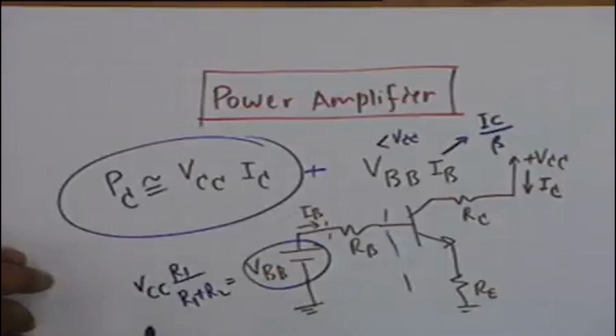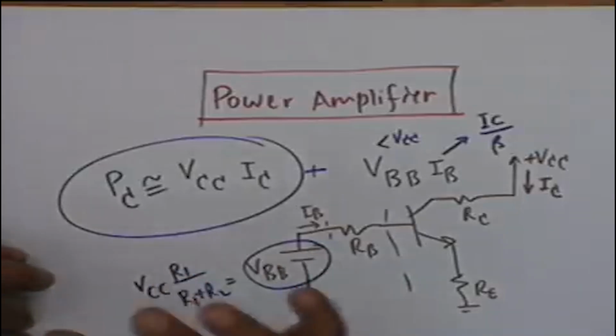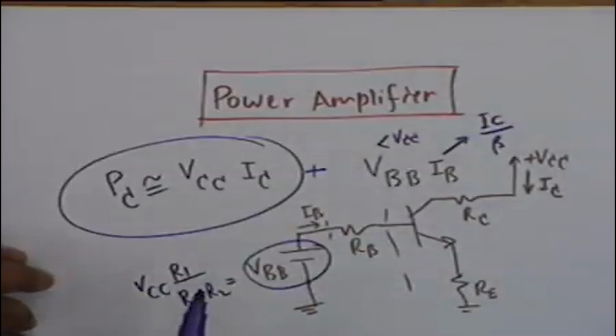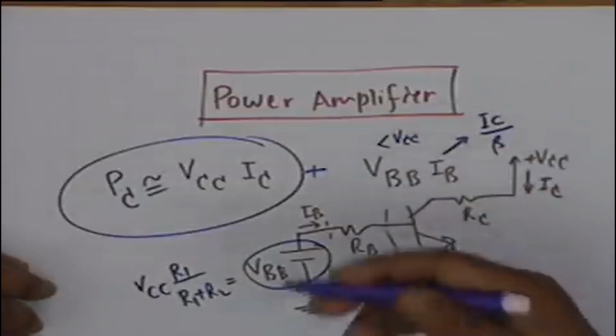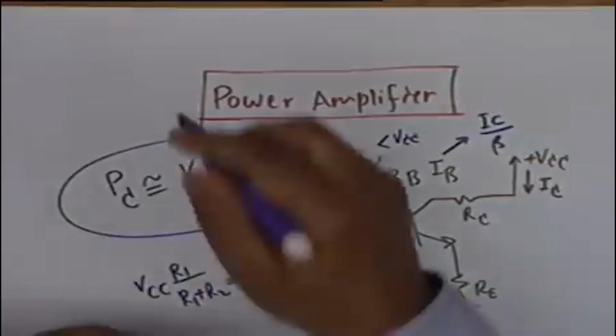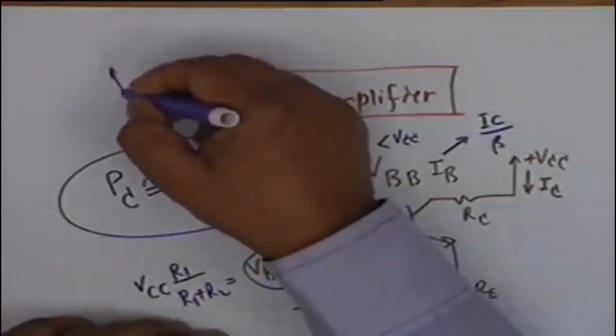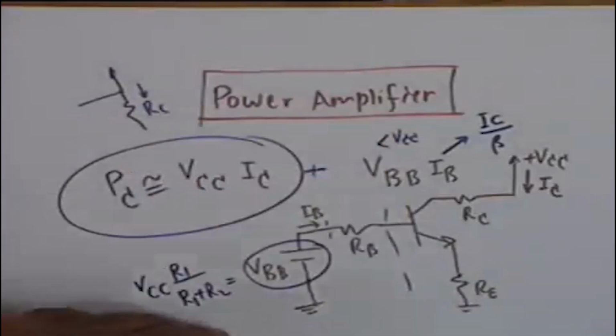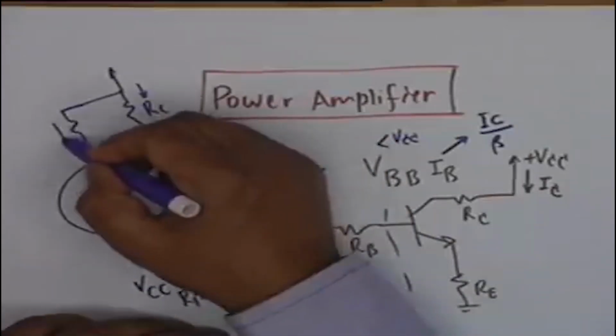In the original circuit, we are not using superposition. We are using the same source but converted to a Thevenin equivalent. This shall be valid. If you calculate from the exact circuit, it will be the same result. This is a simpler way of doing things, because there's a good question that he has asked. What we are doing is, some current is coming through this and some current is going through this.